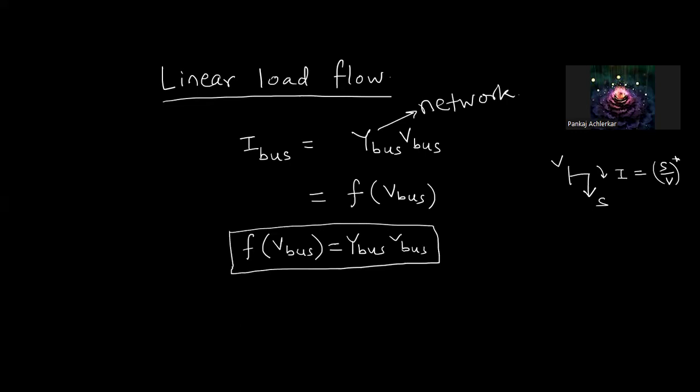Then how do we solve them? We have several methods like Gauss-Seidel or Newton-Raphson in transmission, or in distribution we have seen the backward forward sweep, direct load flow or Gauss implicit Z bus. All these methods are there, and after the end of the iterations, they provide a very accurate solution. The accuracy can be controlled with the help of the tolerance that we set.